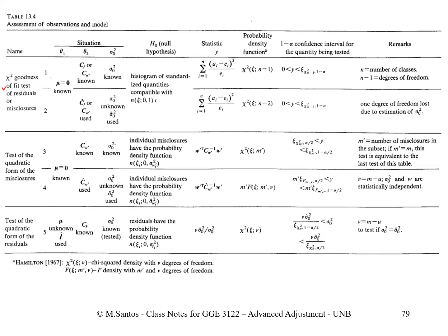It follows the same process of the test of histograms that we did before the adjustment. Okay, the situation that we have as far as the population parameters is concerned is that we know the mean value, because the mean value of residuals and misclosures is expected to be equal to 0. So this is the population mean.